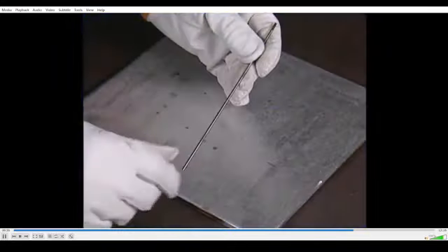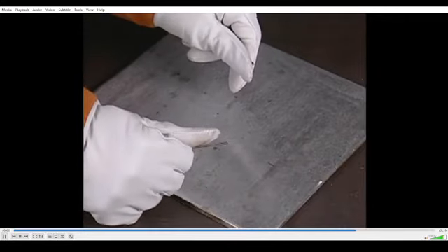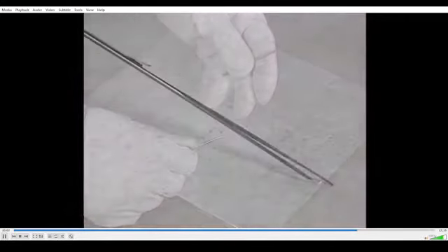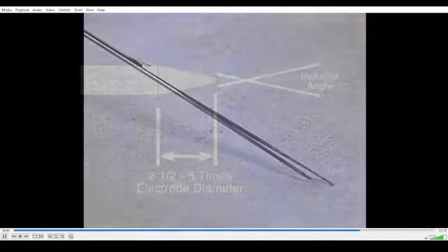A high-quality tungsten electrode is brittle. It should snap when you try to bend it, indicating a fine grain structure. Poorer quality electrodes tend to develop longitudinal cracks that can cause the arc to wander.